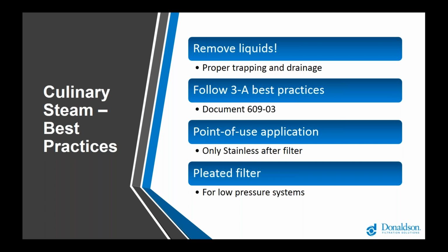It's better than nothing, of course, but it really doesn't address all of that contamination which is generated in the pipes between the filter and the point of use. So the recommendation here is place the filter at or as close to as possible the point of use, and then use only stainless steel after the outlet of the filter to minimize the chance of any corrosion or new contaminants being introduced to the fluid stream.